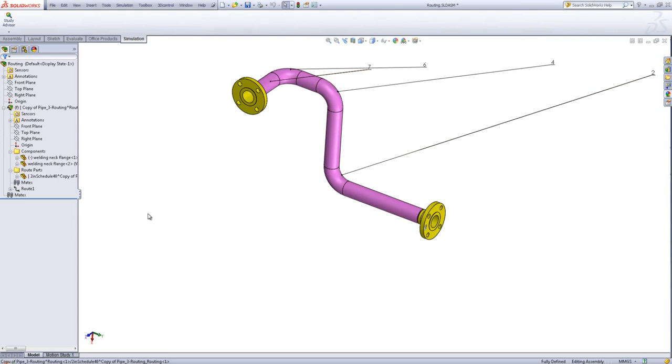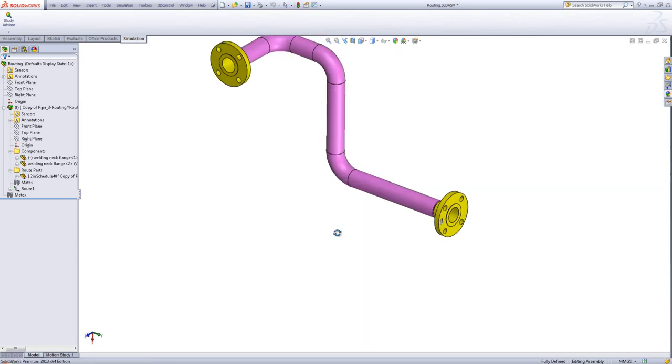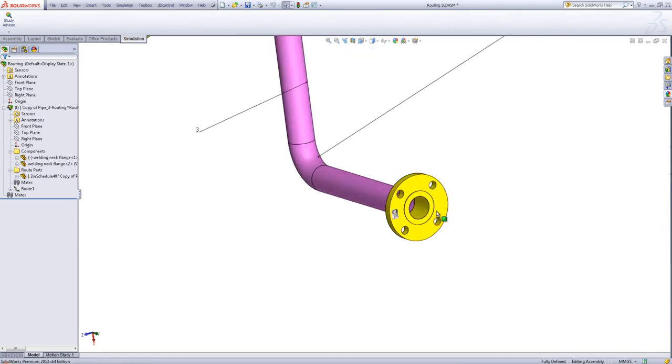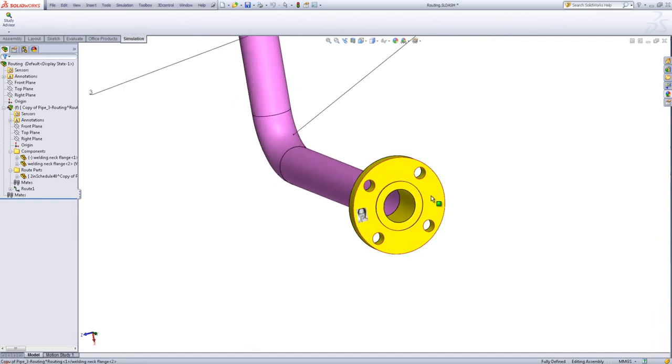So instead what I'm going to do is use a two-dimensional mesh, or a shell mesh. Hopefully if you've been catching up on previous videos, you'll be aware of what that is now. So what I'm going to do beforehand, just a bit of pre-processing, is generate a surface body so I can negate this solid pipe now from the get-go, and then SolidWorks will be up and running, ready to go from there. So I'm going to switch to my surfaces toolbar.